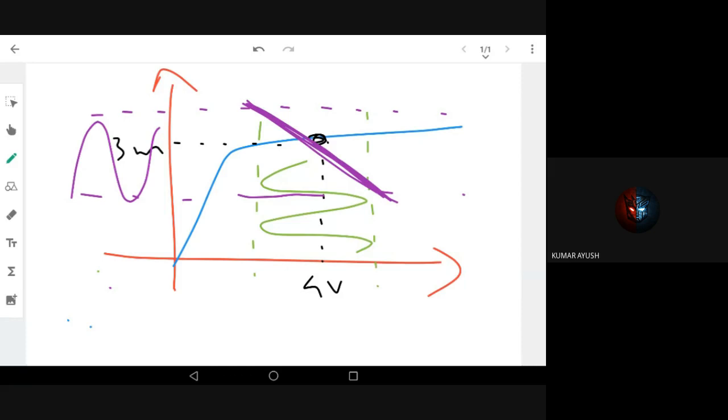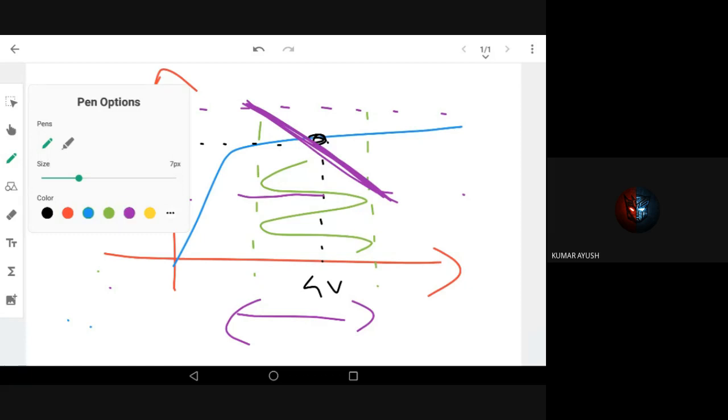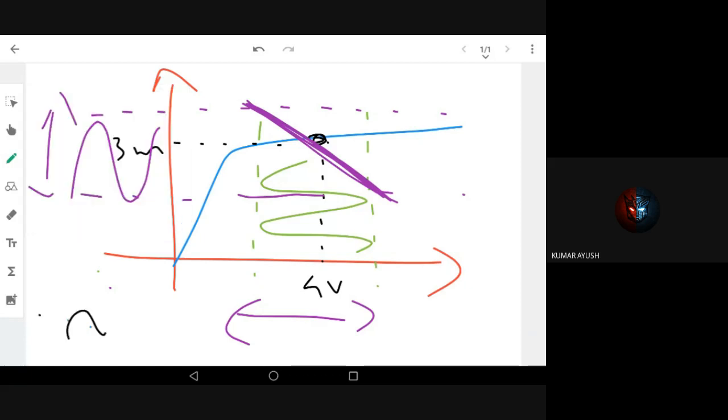This is varying here, and varying here also, and this is much higher. This variation is because of the variation in my base current. The base current is slightly varying here, like this IB. So this variation will produce a greater variation in the output characteristics, voltage and current. So ultimately the signal is amplified. Why? Because of the DC. We are fixing the DC stable or biasing point of a transistor. If you fix the DC point of a transistor nicely, you'll get correct output.